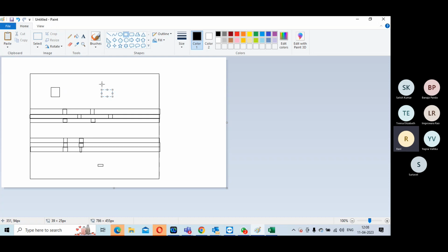You create small regions at a distance of 200 micron everywhere, and tag them to the spare cell. So all the spare cells will sit over here. They are not supposed to move away from that. It is a bound, but it's a fixed bound. This bound should not be moved.